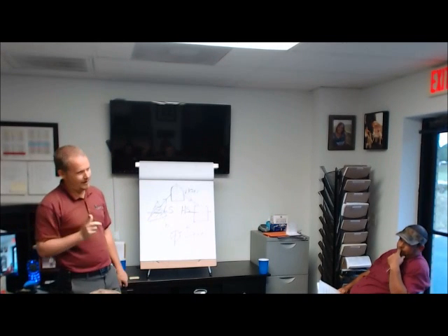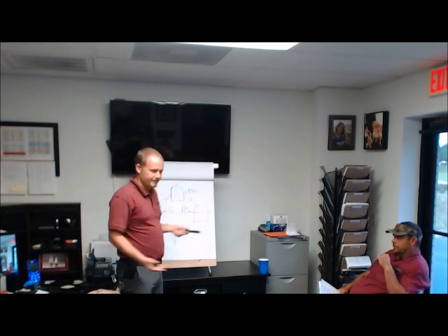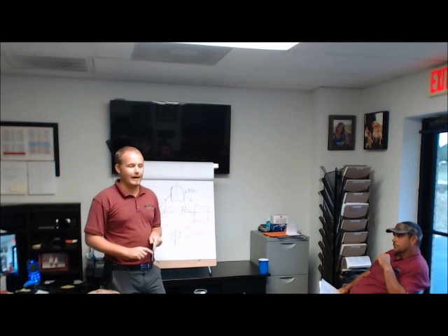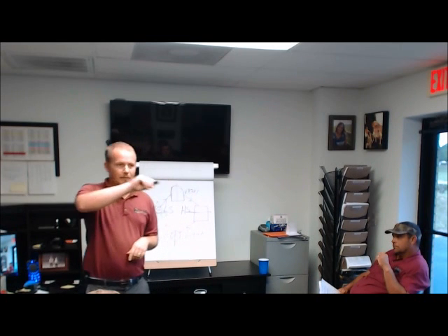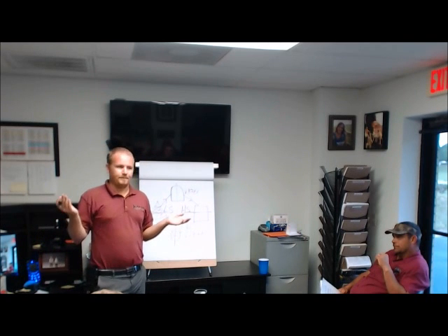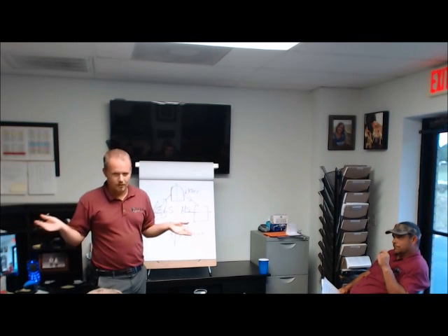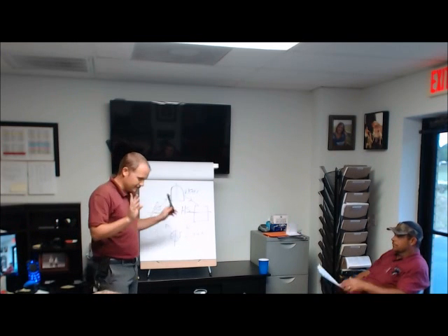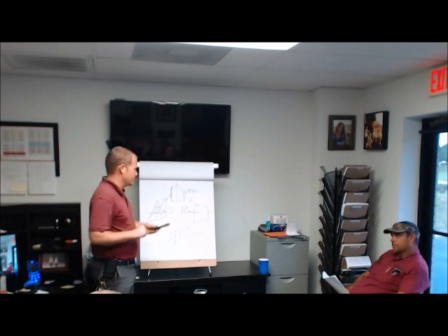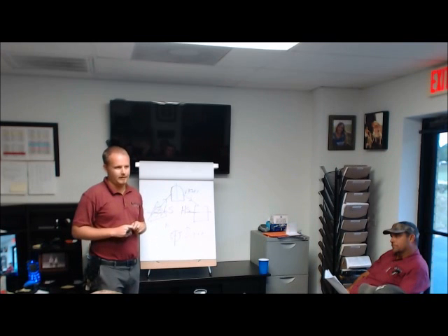Here's the important thing. I had a guy who I worked with, a good technician, who would write up on his invoices negative superheat. He would write down, superheat, -2. Does anyone see a problem with that? Because negative superheat is what? Subcool. And so what he's saying is, because what does subcool tell you? That it's liquid. It's fully liquid. So what he's saying is this suction line is 100% liquid. Is that possible?